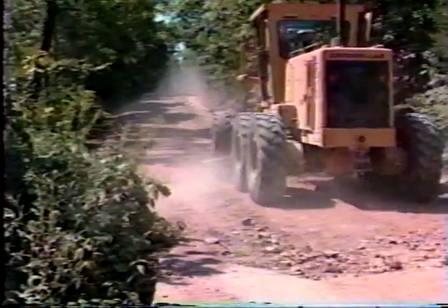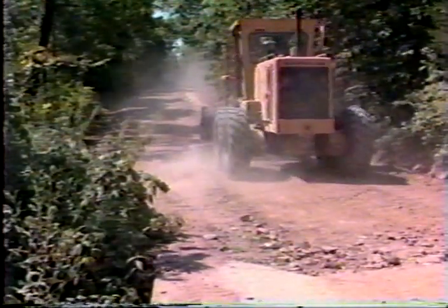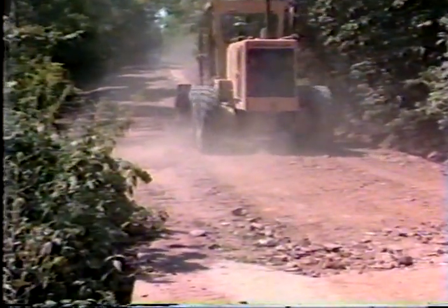Gravel roads are constructed of loose aggregate bonded together with a mixture of sand and fines compacted by traffic. With normal wear, the surface of a gravel roadway becomes unbonded and rough. When this condition occurs, the roadway needs to be smoothed. Smoothing might best be described as the redistribution of the loosened aggregate back onto the roadway.